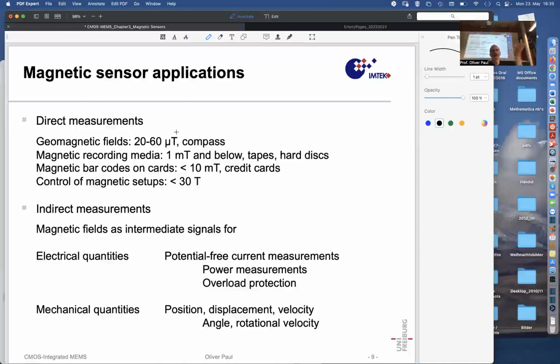And then the analog circuit designers, who should extract the signal from the noise or offset, don't like microvolts because that's really small. They would like to have millivolts. Microvolts is the limit. You can do it, but you need a lot of compensation circuitry, and it's hard.